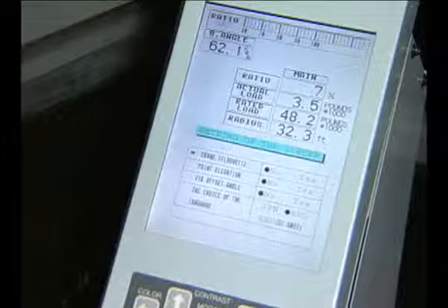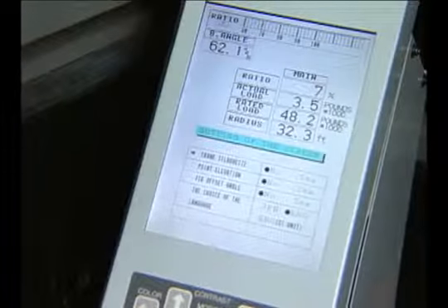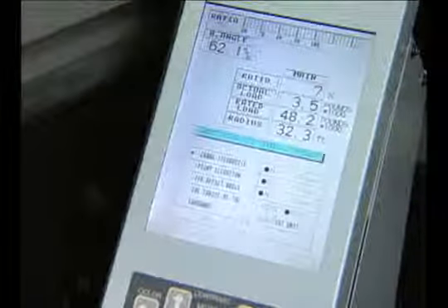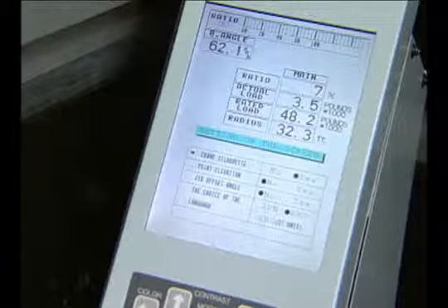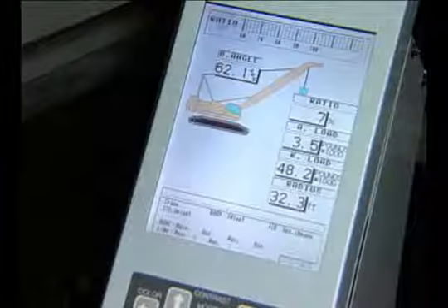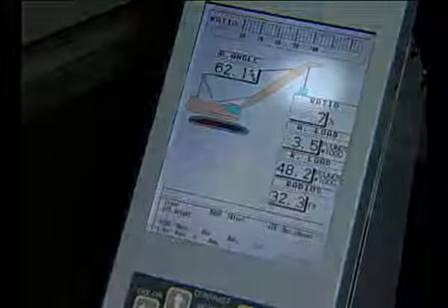In the Setting of the Screen mode, the operator can choose a crane silhouette on the main display screen. To demonstrate this, we will choose Yes and push Set. This gives a picture of the crane on the main display screen. In this screen, the operator must watch the load on the boom tip to shift when the mode button is pushed, to indicate the use of main or auxiliary hook.